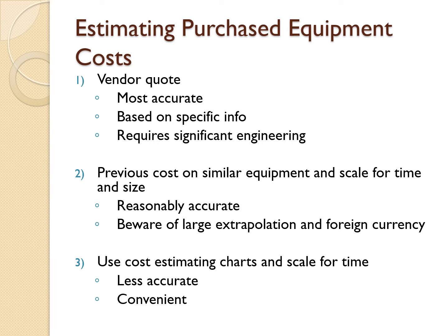Comparing the 3 methods, the vendor quotation is most accurate because it is based on specific information and requires significant engineering. That means we already have a completed design, and from the completed design, the vendor gives a quotation. That one is most accurate. For the second one, the accuracy is reasonable, but we need to beware of large extrapolation and foreign currency, because we are dealing with scaling and the indexes for costs.